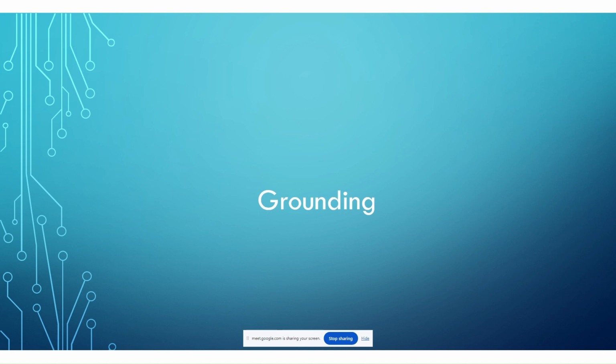So we really have multiple problems here that can be solved just by having a good ground throughout your PCB. Now, the other thing I would bring up here with grounding is that once you get to more advanced designs, and I'm going to qualify what advanced means, once you get to more advanced designs where you do have very fast digital signals, the right grounding strategy in your stack up also influences power integrity.